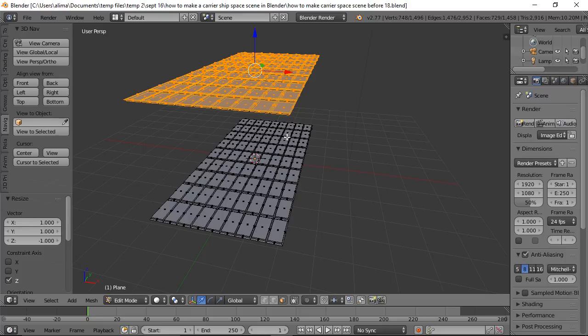So Blender does decide how the faces are going. So just from working with Blender, I know that these faces here are pointed up. When I duplicated this geometry right here, the faces still would have been pointing up. So I wanted the faces pointing down. So that's why I selected this, pressed S to scale on the Z-axis -1.